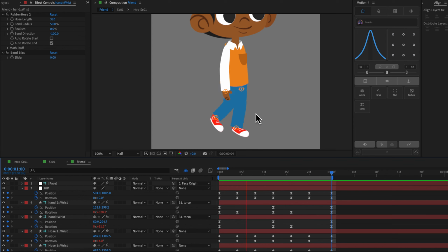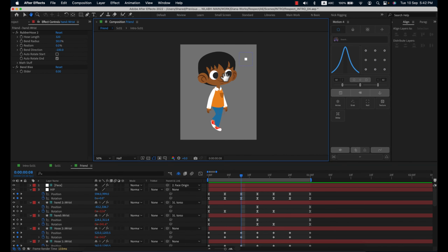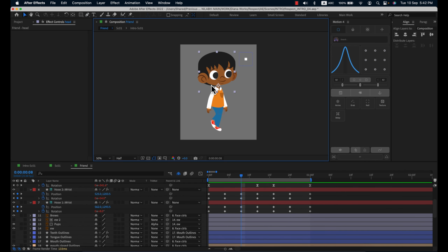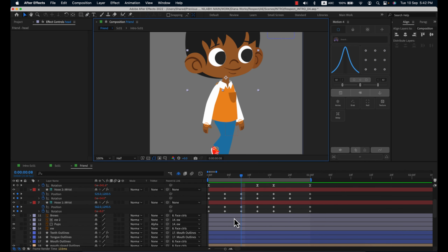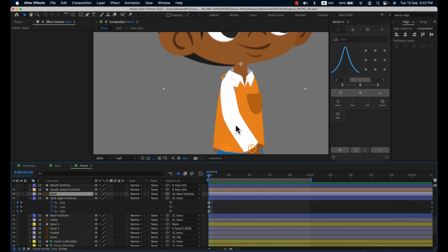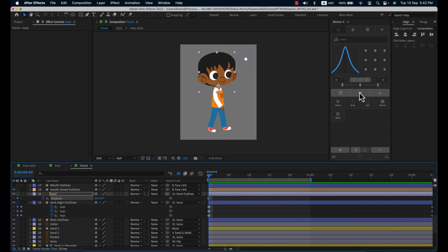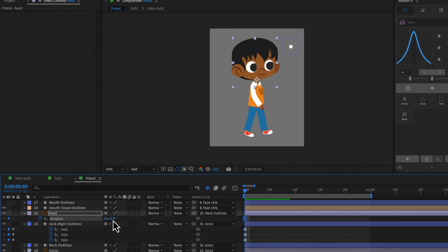Alright, our hands and legs and hips are very well sorted, and you can see the walk cycle looks pretty natural and good. Now we need to animate the head and the face. Okay, let's select the head. The pivot is set at the neck, which is where we want it to be, and we are only going to put keys on the rotation. So let's press Option or Alt R to key the first frame. Let's give it ease. I'm just going to make him look up a little bit, so maybe -4.